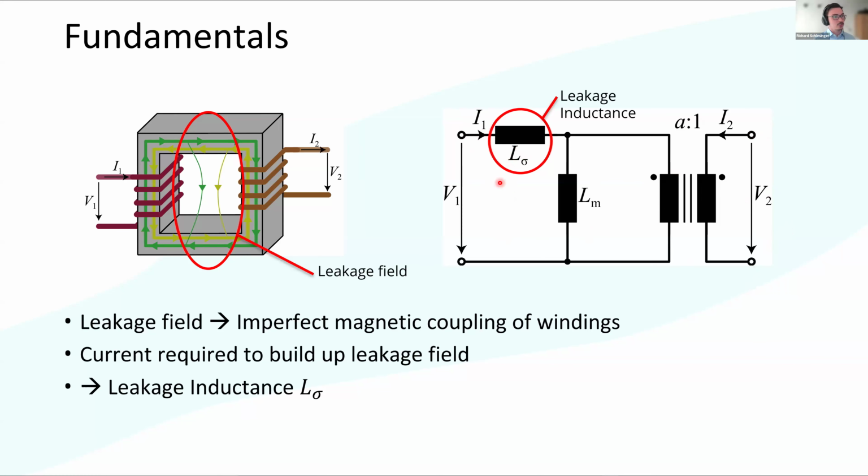What you then do is bridge the magnetizing inductance, and in theory, you would only see the leakage inductance. But this is theory. In reality, this short circuit will always have a finite impedance, which is why in the low frequency regime you mainly see a very high inductance, but this is the magnetizing inductance. So this is in general how it works.